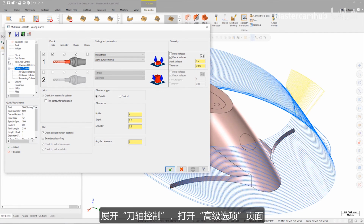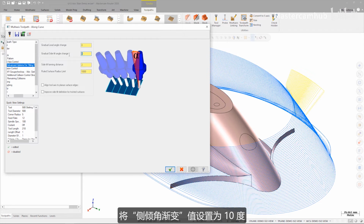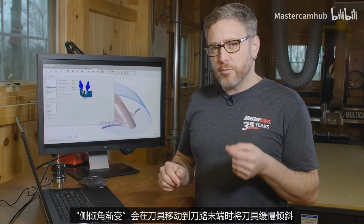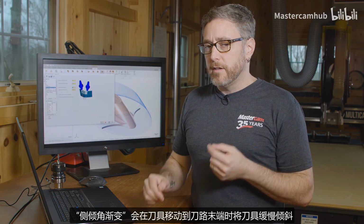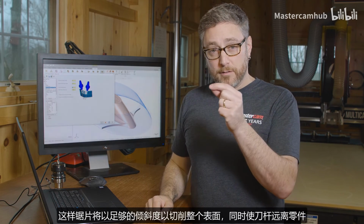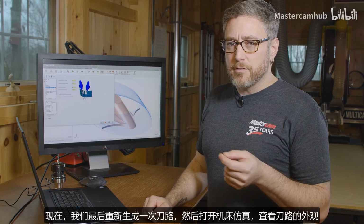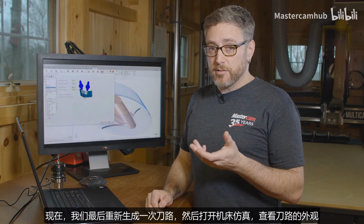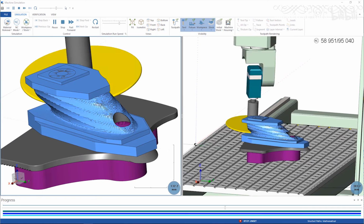Let's expand the tree for tool axis control and select the Advanced Options page. Set the gradual side tilt angle change to 10 degrees. Gradual tilt will slowly tilt the tool as it moves towards the end of the tool path. By doing this, the saw will have enough tilt to cut the entire surface while keeping the arbor clear of the part. We can regenerate the tool path one last time, and we'll launch machine simulation to see how the tool path looks.